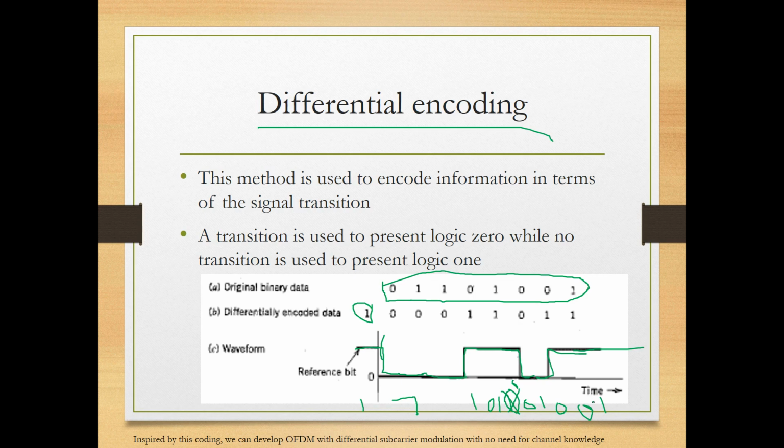But if you apply differential encoding for your whole packet, if one bit is in error, your whole packet is in error. But for small sub-blocks, you have a chance to correct yourself at the beginning of each block, to start again fresh, with no mistakes. Yes, is that clear? This is very important, very useful, and it's used in many practical communication systems.